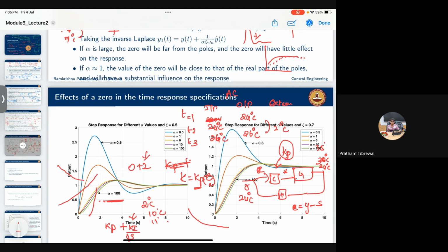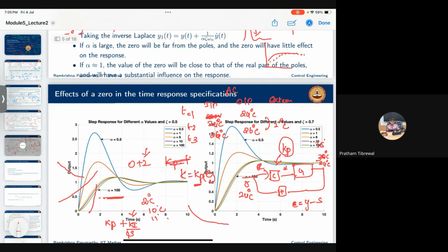See, it is accumulating the error. So after a period of time, if the error doesn't go to zero, the overall error will be high. So it is going to generate a control action that is also high. So this will increase the overshoot in the system. The output response will be abrupt.